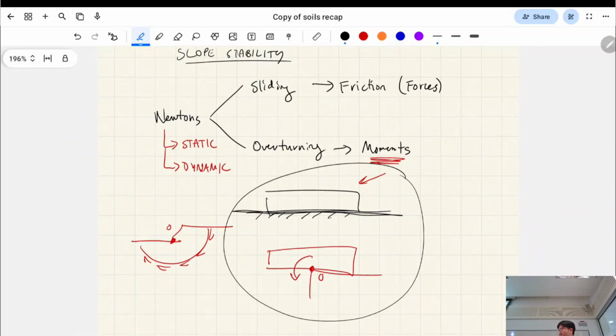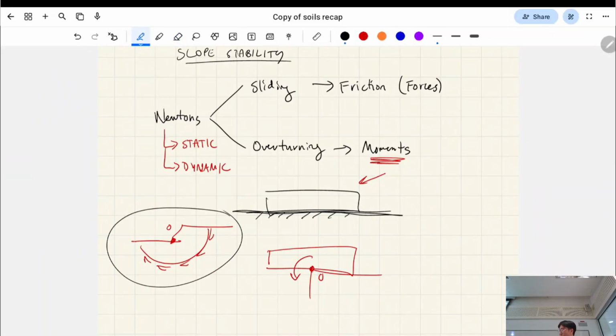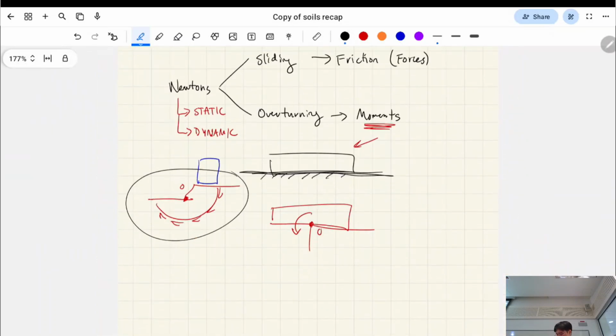But you'll notice, and the reason why I talked about a concrete beam breaking, even in the context of a concrete beam, the material itself didn't actually rip apart. It's not a material failure. It's all to do with forces causing it to become dynamic or moving, whereas it started as static. So when we're talking about it in the context of soil, this soil is static. It's not going to move, right? But if you put a building on it like this, it might slip and become a dynamic moving system. And we don't want that because that's dangerous, obviously. That's what instability is, essentially.